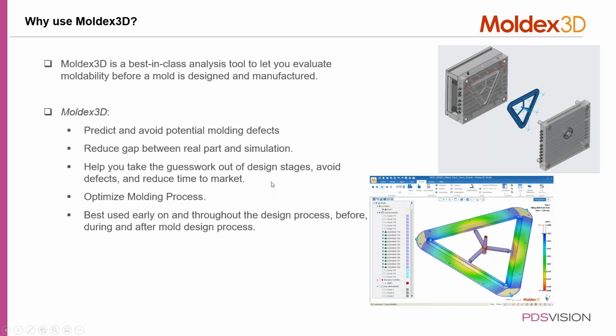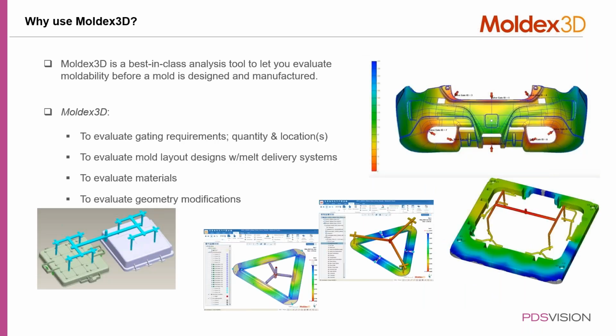But also, even when the tool has been designed, it's a good check to make sure that once you have better ideas on, say, the cooling channels, the location, everything, where it's at, to rerun the analysis to make sure that it's going to meet your processing requirements.